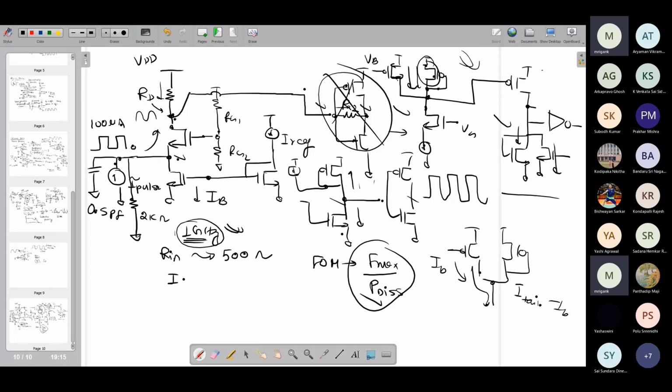So those things you should be aware of. So I think you get started on this, and it should not take much time. It's a small circuit only. Any gain specifications are like we have 0 to 100 microampere at the input. I've already told you that the output you need full swing. So here you should be able to derive that I need almost full swing at the inverter output. So what signal over here will give you full swing? If you go a few hundred millivolt for this inverter, it will give you close to full swing. So maybe assume that it is 500 millivolt peak to peak at least, or maybe more than that.